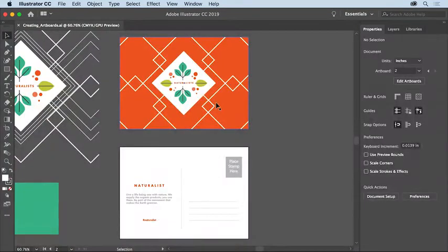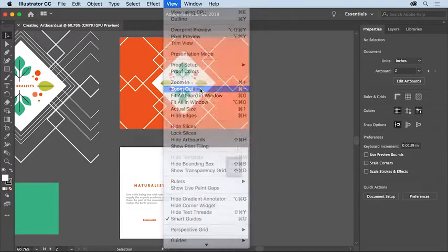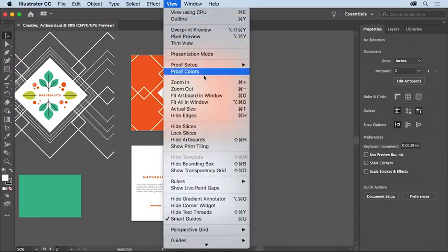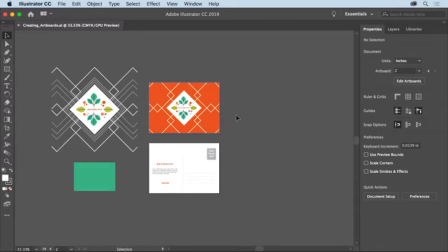With this practice file open so you can see everything, choose View, Fit All in Window. Then, so you can see more of the gray area to the right of the artboards because you're going to draw an artboard out there, you'll zoom out. Choose View, Zoom Out a few times. The artwork you see on the left is in the gray canvas area.